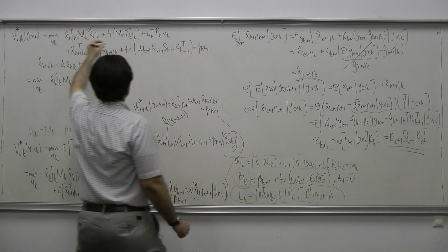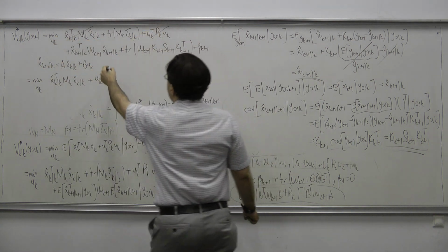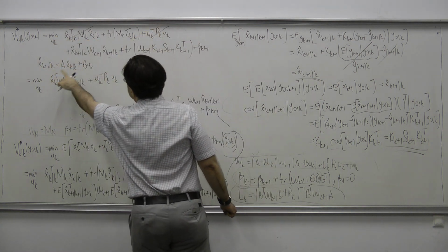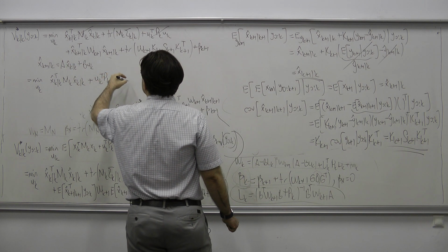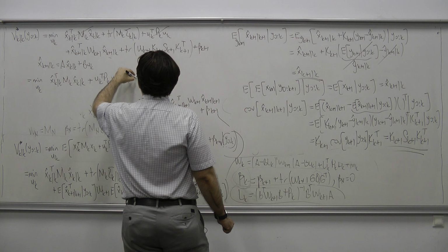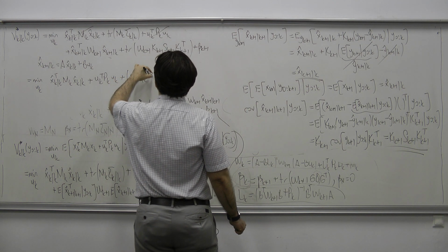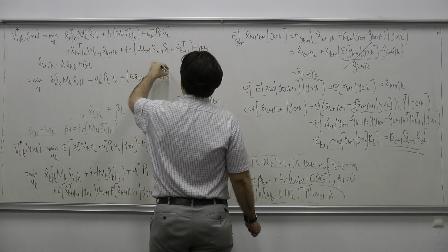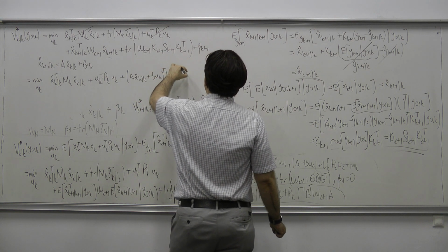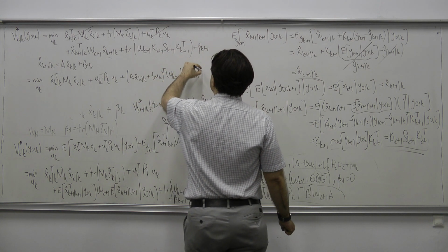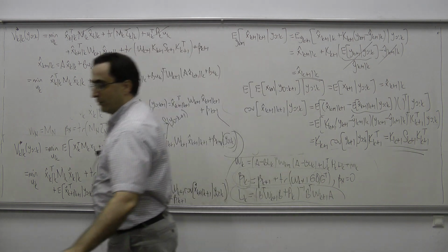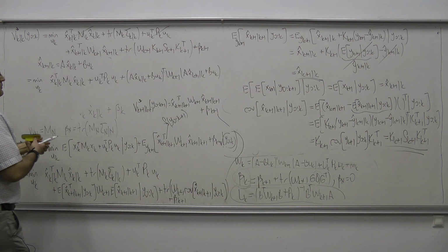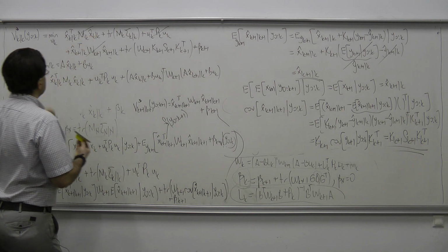So I handled this, and then I have this term. Then I'm going to use the prediction covariance, predicted estimate formula. So I have A x at k given k plus B uk transpose W k plus 1 times A x at k given k plus B uk. So this handled just this term.